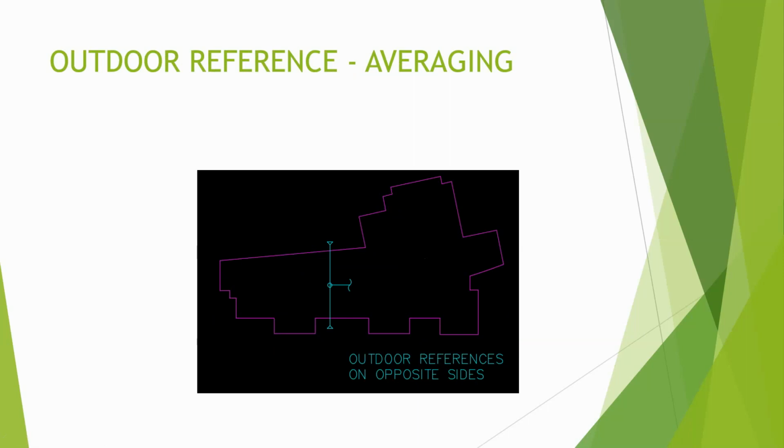So anyway, this is another picture of a way to do a two-sensor array on a building and average that input. So those two sensors are mounted at the same height as the indoor reference. And so at that point, if that's the case, then you don't have off calibration of your sensing array during cold weather.